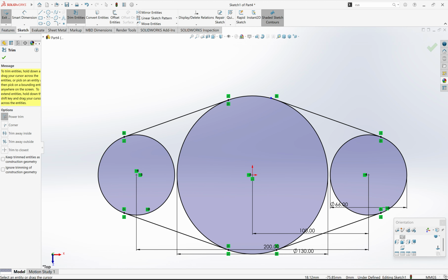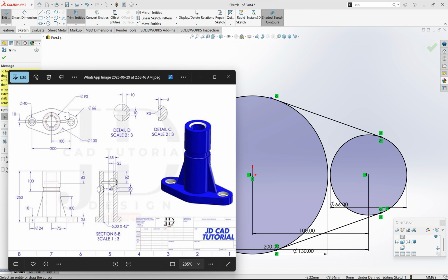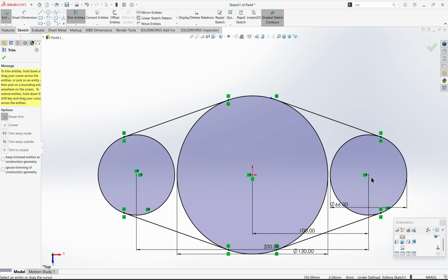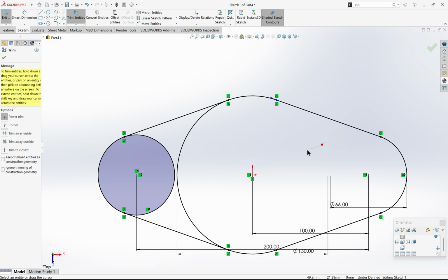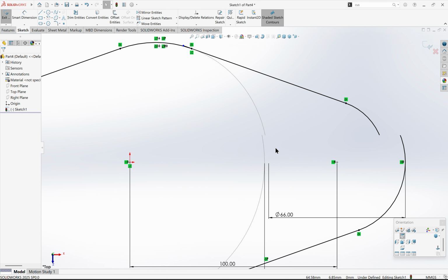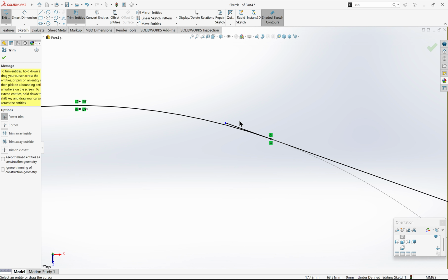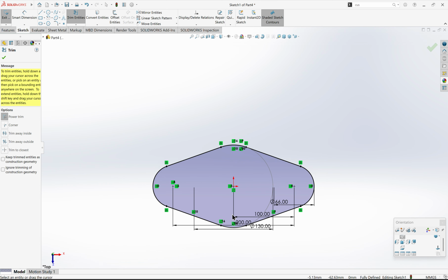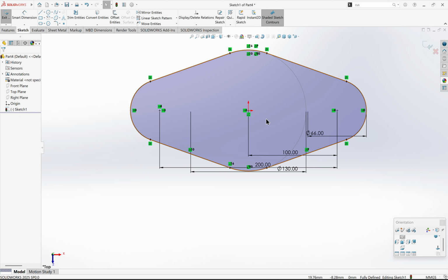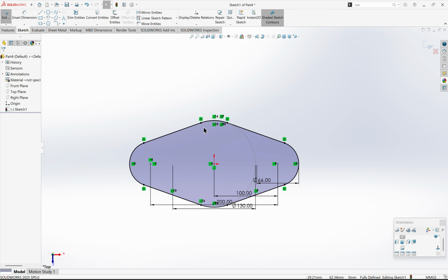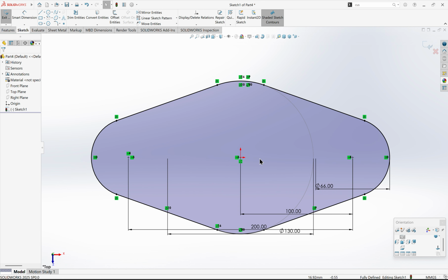Now, from the drawing, it's showing that there's no inner circle, like the inner circle here and here. So we're going to cut them too. Cut this, this, this, this. So we have it under defined. We have the problem over here. Just get the trim tool again and then just cut it. It will be shaded. This shading means that it's all closed, so there's no opening in the drawing.